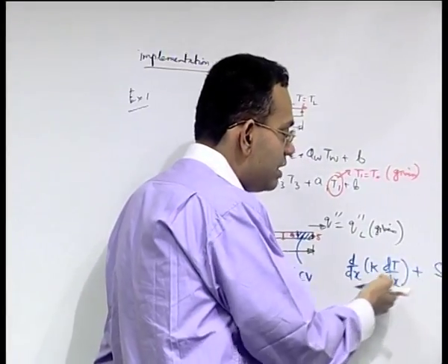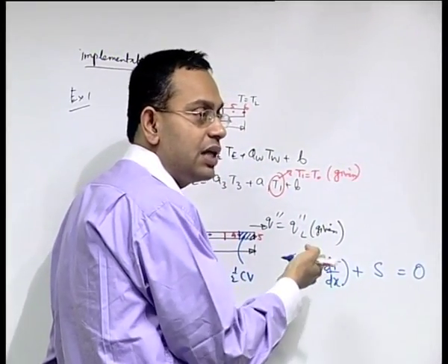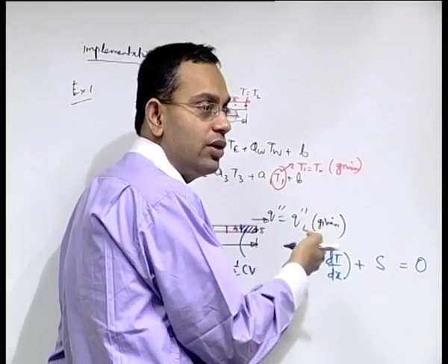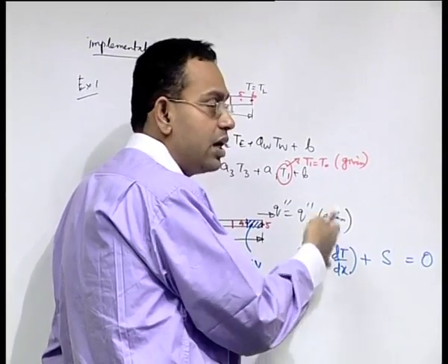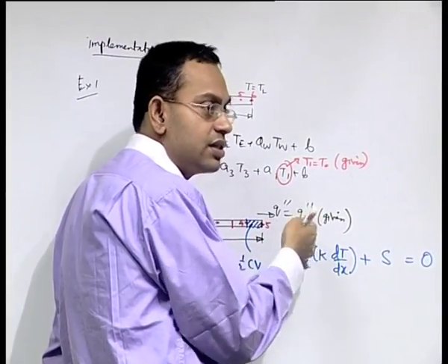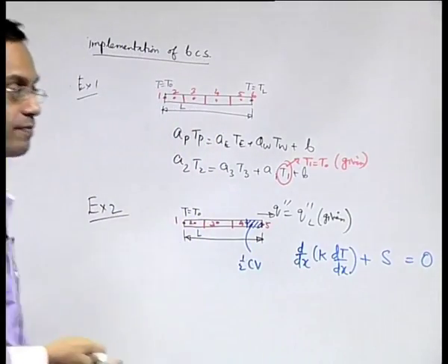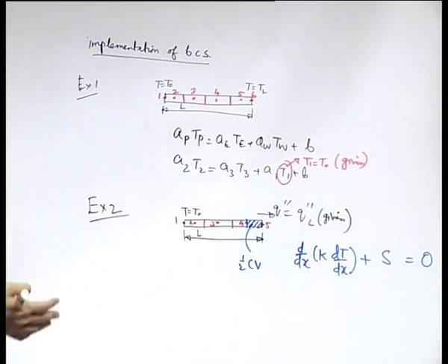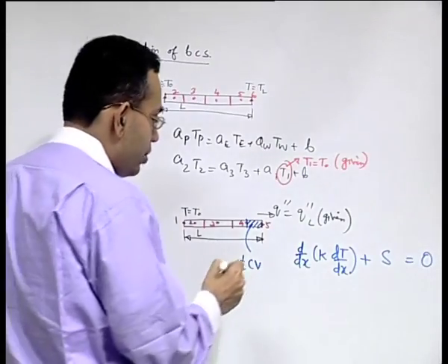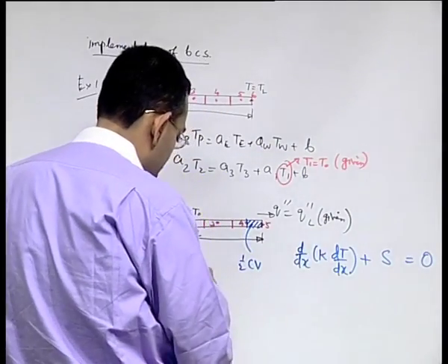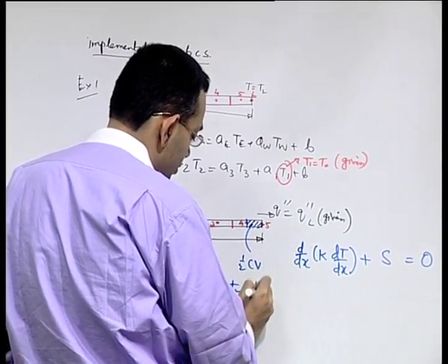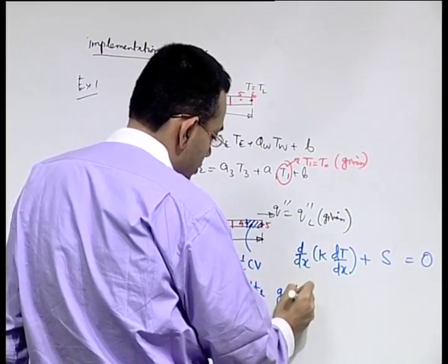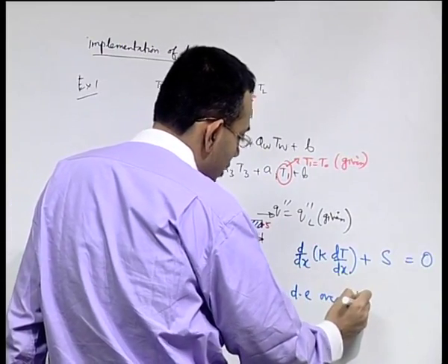Here we have seen that the finite volume method may be interpreted as a special type of weighted residual method where the weight is equal to 1, and therefore a similar sort of confluence may be expected. Let us see whether that can happen or not. So, what we do, we integrate the governing differential equation over the half control volume.